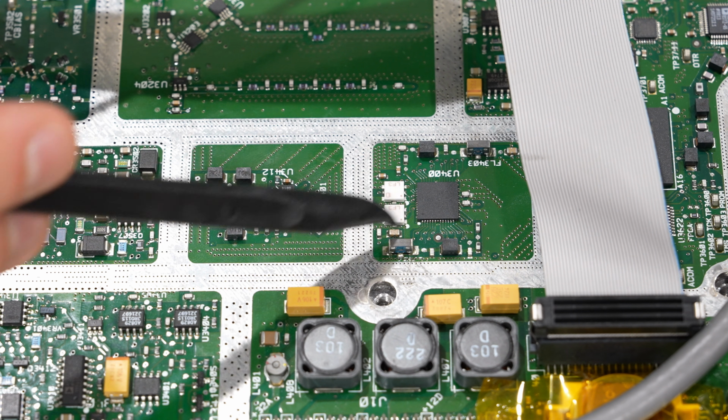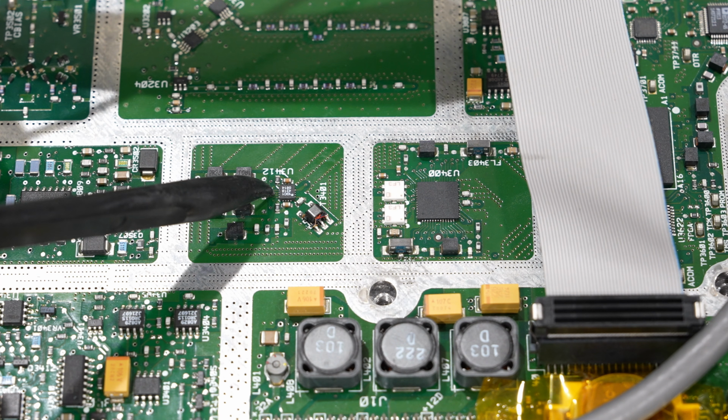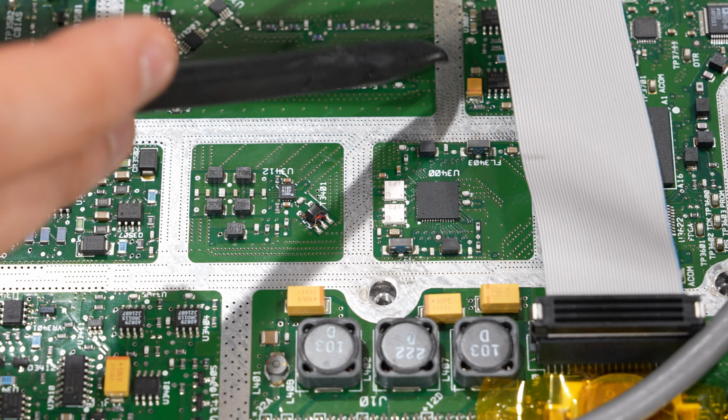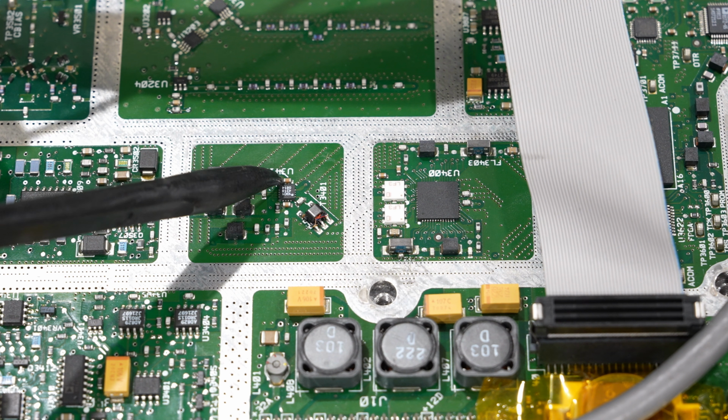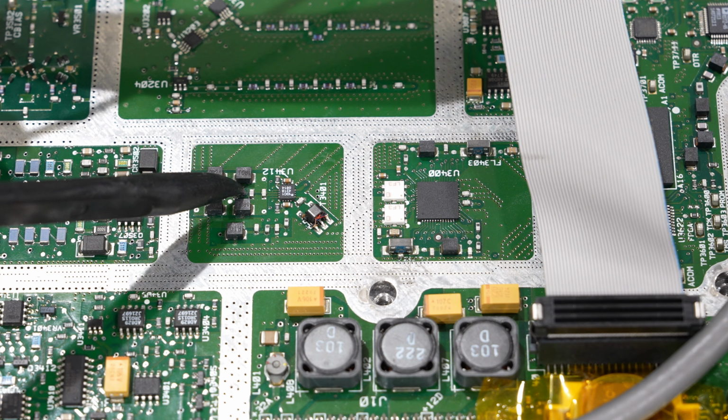What comes out of here is going to be a differential signal, which is converted to single-ended. That's a divided signal, and that goes into the phase detector. That's what has to be 50 megahertz for the loop to be locked when you're asking for the desired frequency. And then on this side comes the reference 50 megahertz, which we know works. It comes from the reference circuitry. So we're going to look at this one and this one, and then ultimately the output of the phase detector.